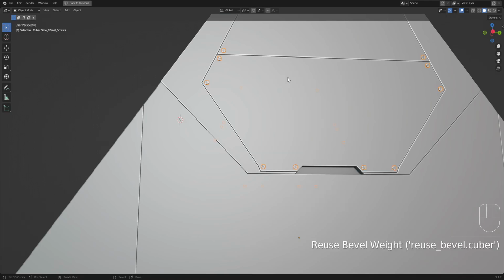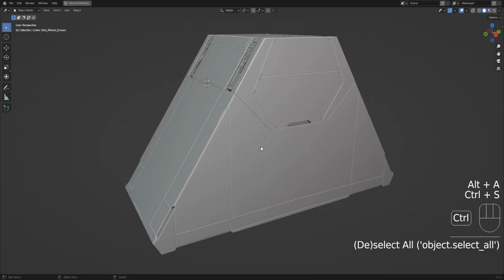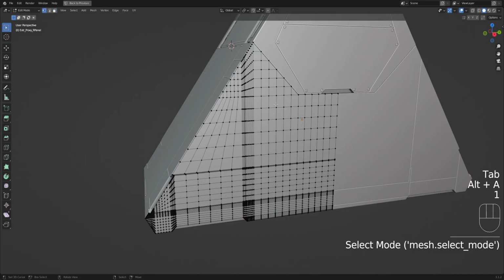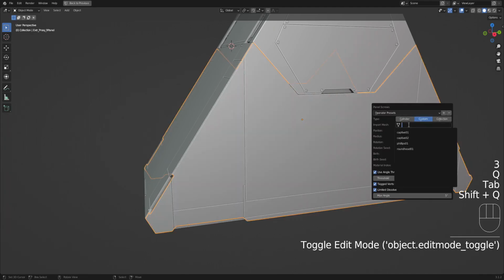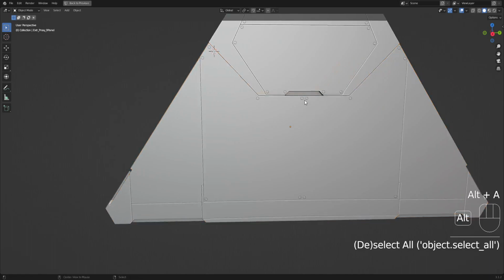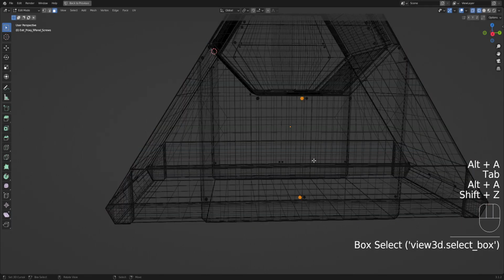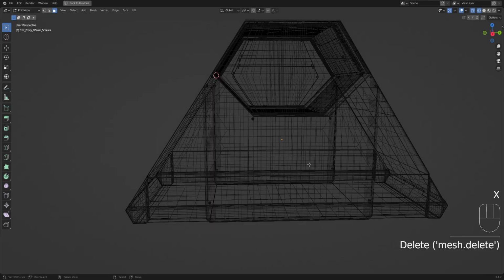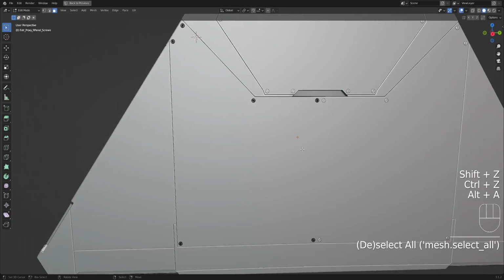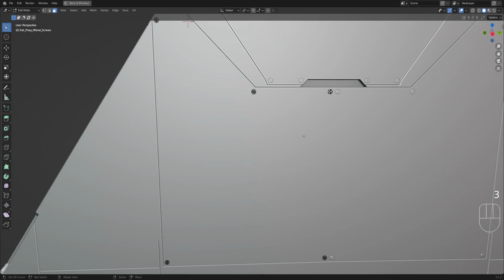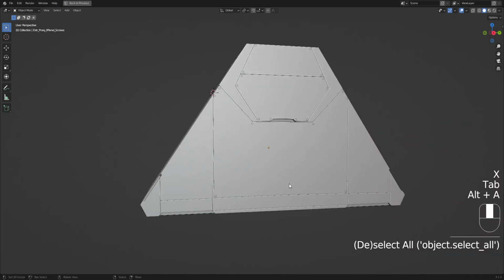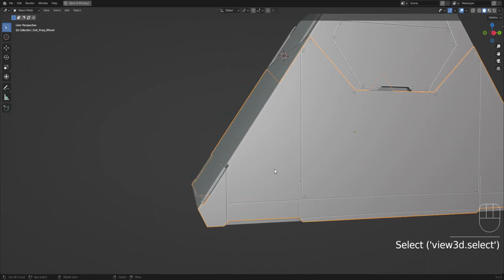And recycle or reuse the bevel weight from before. Okay. This one as well. Captive. And let's delete the center. If you forgot to tag the verts, just delete them. Go to X-ray. You can select all the faces, press F. Or you can hover over the faces, if you're in face selection mode, L, that's select island, and X, F to delete the faces. Okay.